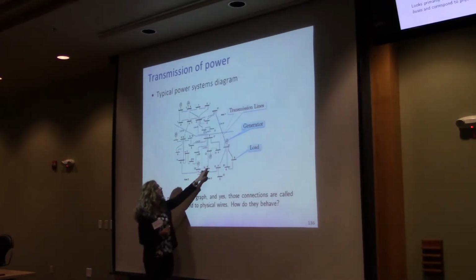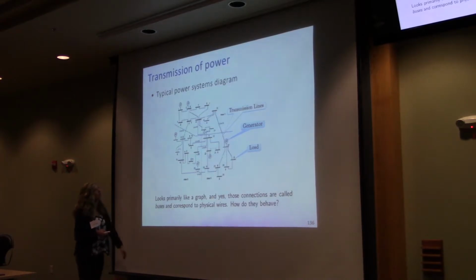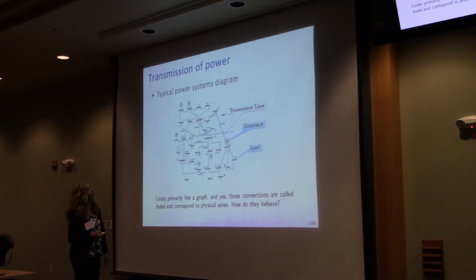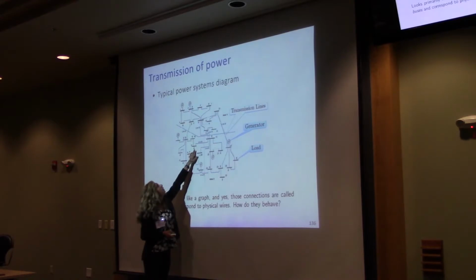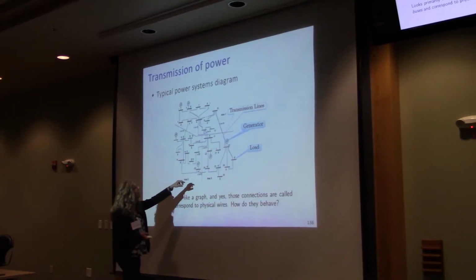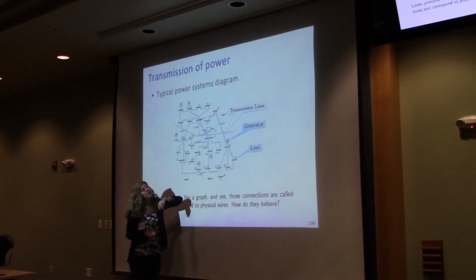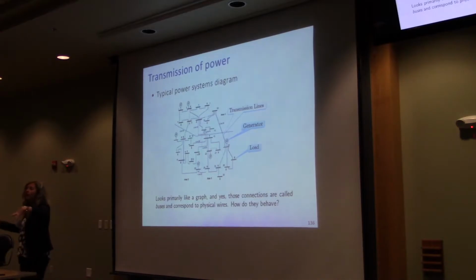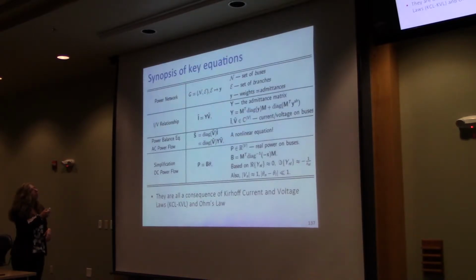And typically here you have transformers that bring down the voltage level from the transmission level. And then you have other points that are intermediate points, and all of these nodes of the network, whether they have an arrow, so they go to a feeder of some sort, or they don't have an arrow, like this guy, number 9 up there, they are intermediate nodes. They're just interconnecting multiple lines that are splitting. So all of these are called buses. They call it a bus, okay? And so let me give you here a summary of the equations that I will go through.